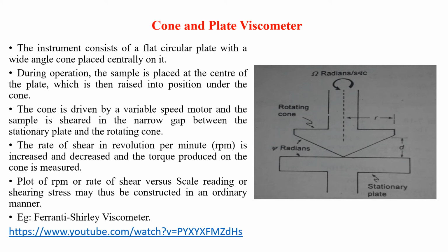Right? So the only simple thing is we'll be calculating the rate of shear with shear stress. Do always remember rate of shear is expressed in terms of RPM and shear stress is expressed as a torque experienced or the stress experienced.